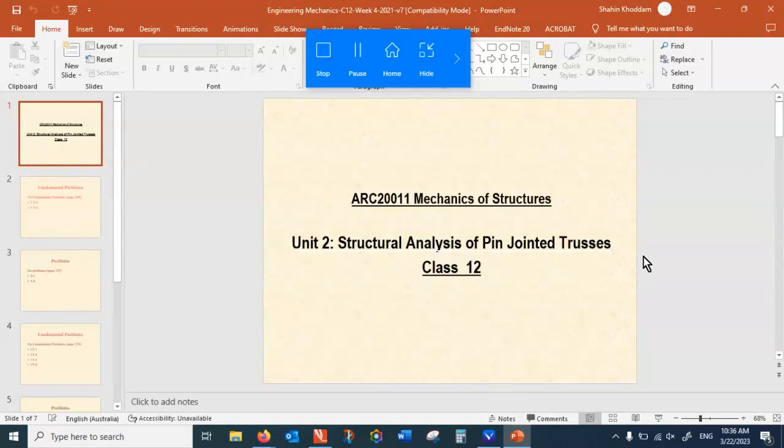So what you need to know is a truss is made of two common components. The first one is a pin. The second one is a two-force member. So I'm sure you've done these Lego things, you put things together. So think of a truss structure like a Lego. There are pins, there are two force members, and you push pins inside the one end of the two force member, and you can pass the pin through several or two, at least that's two, right? So that's why we call this a pin joint structure.